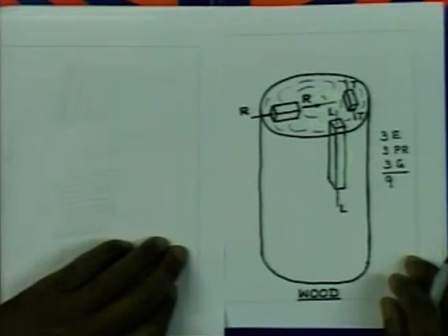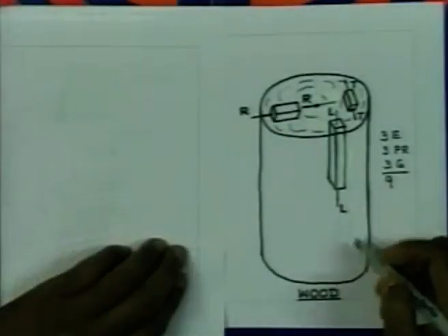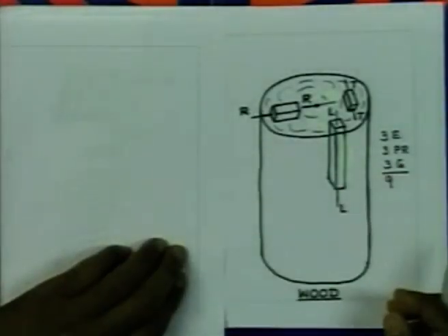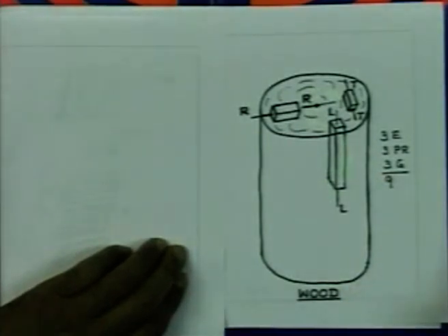But in the case of purely anisotropic material, the number of elastic constants would be 21, which we will show you a little later. Now, in the case of timber, you take these three directions anywhere in the whole trunk of the tree, they will show similar properties. So, these are known as material symmetry directions. That leads to some advantage.